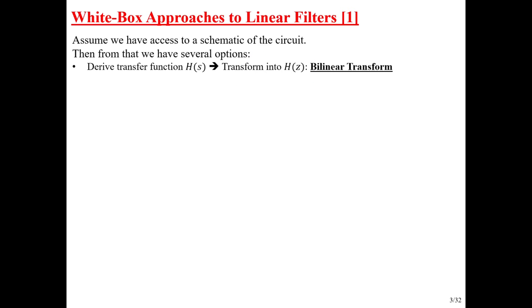In MATLAB, we would use the filter command, but in a real-time implementation, we'd have to write a little loop that computes the recursion of that difference equation. Notice that I don't indicate that that comes out of David Yeh's paper because he doesn't really talk about that there. But we've talked about that already, so you kind of know how to do that.